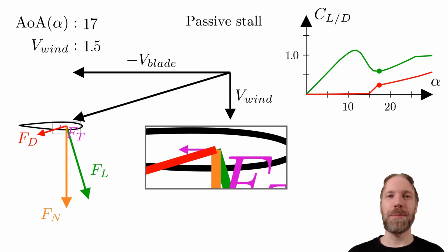Later, turbine manufacturers started to add pitch mechanisms to the turbine. This allows the blade to turn during operation. Now we can use this to reduce the power to any value we want. There are two options now to reduce the power. If we operate at the optimal point, turning the blade in either direction should decrease power.